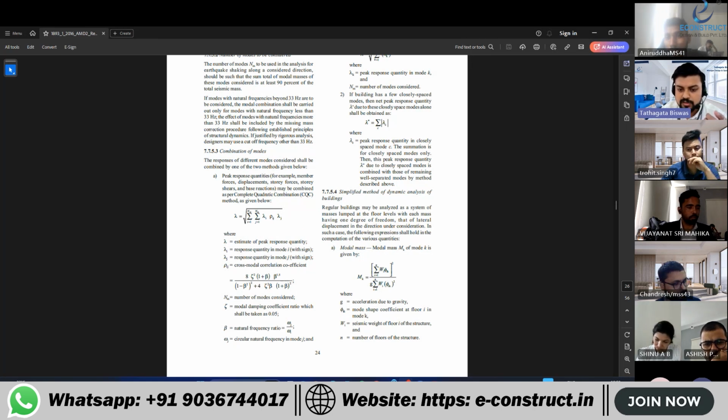Response spectrum case is there, no, Spec X and Spec Y. Over there is a modal combination type where we keep it as SRSS. So this needs to be made as CQC. Okay, so this is how CQC is done.